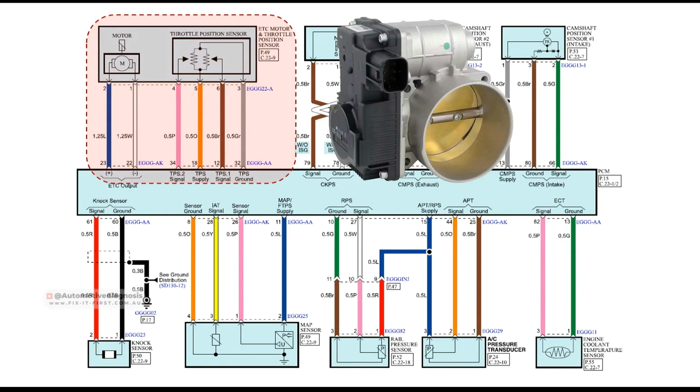The throttle body is very important for the proper operation of the engine. Anytime you accelerate, when you press the gas pedal, you are actually sending a request to the PCM, and the PCM is going to open the throttle body to provide more air for the engine. Opening the throttle body happens through an actuator, but for reading the current position of the throttle body, we need 1 or more sensors. In this case, we have 2 sensors. These sensors are potentiometers providing variable resistance based on the throttle position angle. So these sensors are called TPS1 for throttle position sensor 1, and TPS2.